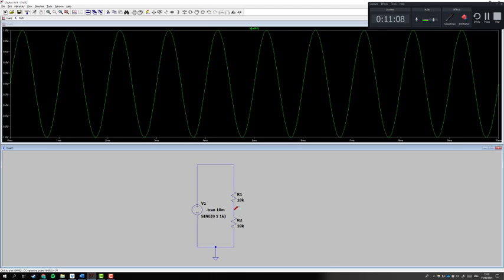And if we click in the in-between part, you'll see, this is probably a little bit difficult depending on your YouTube, but there's a blue, quite faint, oscillation here, which is at half the amplitude. So whereas the voltage source gives plus or minus 1 volt, we now have plus or minus half a volt. So that's your basic transient analysis. What is happening in time?